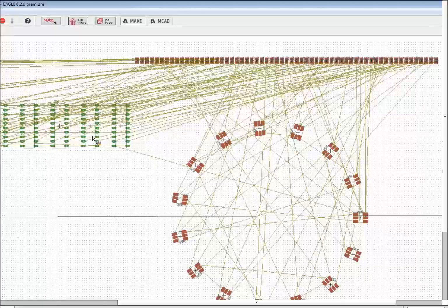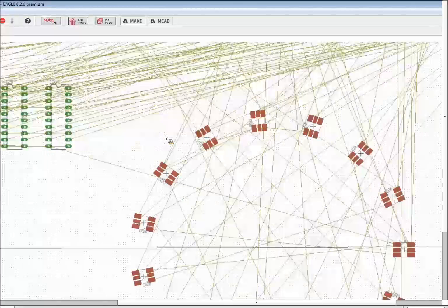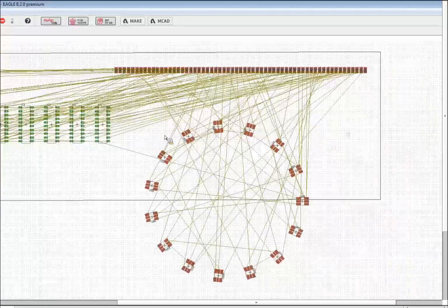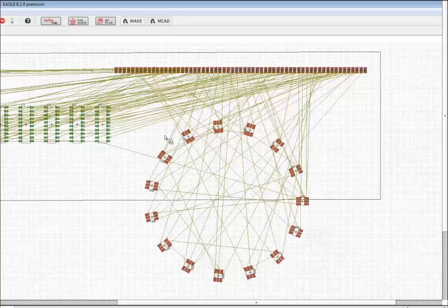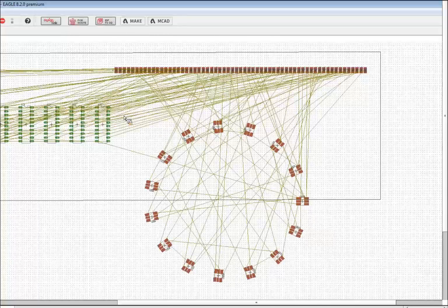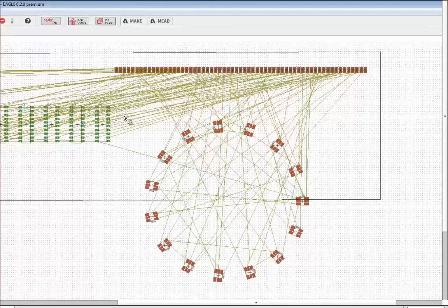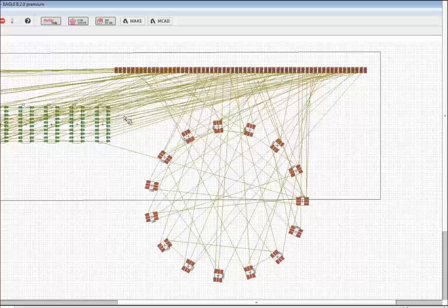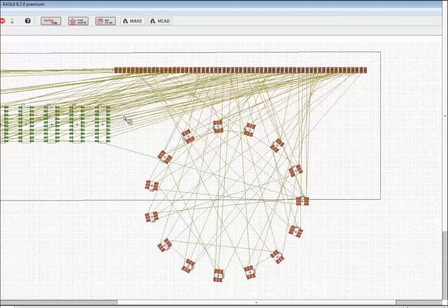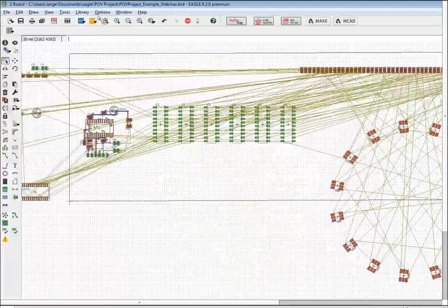So I don't see any other questions. In this webinar, we're talking a little bit about once you go from your schematic to a board, what are the things that you could do? What can make it easier for you? So the alignment tool is always a great idea. And now that we have this done in this version of Eagle, it really helps out, automating quite a bit of the process. In the past, you always had to do this one by one, hoping that you would get alignment by using a long X and Y type of mouse cursor. Now that's no longer needed.